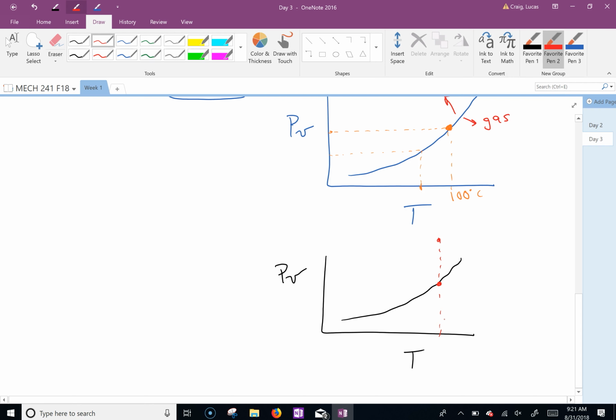If we're here, at one constant temperature, and we drop the pressure, boom, we start getting air bubbles. And then boom, it's all vapor underneath it. So there are two ways you can make liquid change into a vapor: keeping the pressure constant and increasing the temperature, or keeping the temperature constant but dropping the pressure.